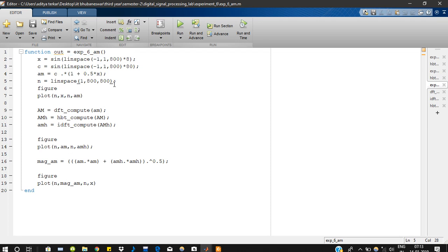In my case, I have performed the Hilbert transform using the Fourier transform method. We need to understand that we have a discrete time sequence, as in MATLAB this vector is going to be of discrete values.